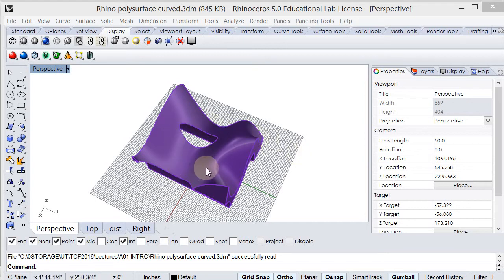It's watertight, airtight, doesn't have self-intersections, doesn't have non-manifold edges. It's just no open edges, that kind of thing. Revit will see it, but it won't see it as a solid. So you want to make sure that you've done that. The other thing I would recommend is just center it on 0, 0, so at the center of Rhino. It just makes it easier in the import-export process.